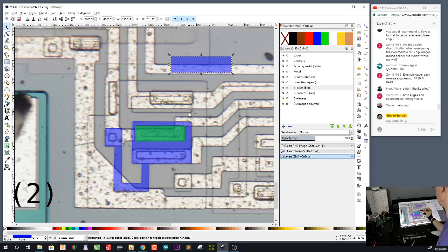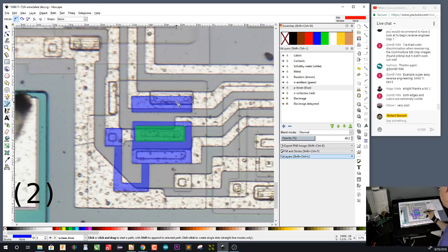This, on the other hand, is kind of off-center, and kind of larger than it seems it needs to be. So that's why I suspect that's actually a different doping region altogether. And again, that's probably going to be really confusing right now, but hopefully, if we actually look at it and stare at it and draw it out, it may actually end up being just a diode.